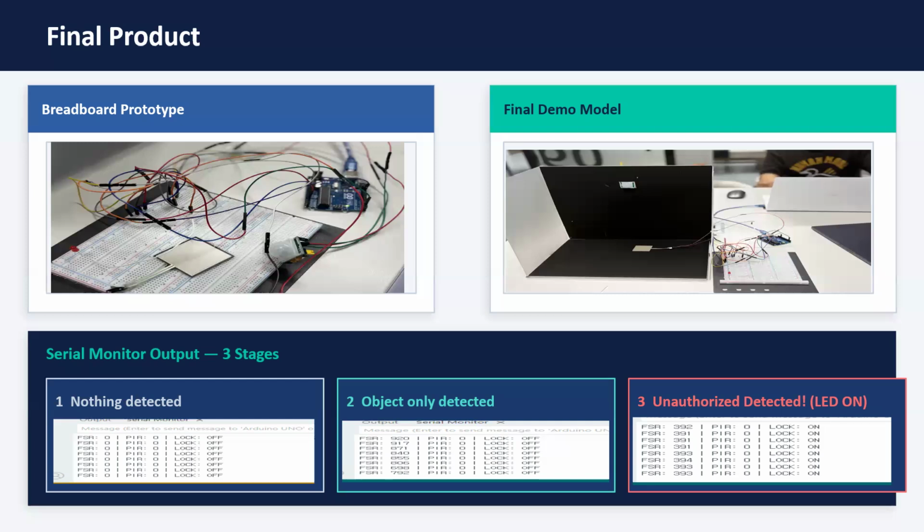Stage 2, the state occurs immediately after a user sits down and or when belongings are placed on the desk, causing the FSR value to increase. Stage 3, pressure continues to be applied to the FSR sensor, meaning belongings are still present but no human movement is detected by the PIR sensor for the preset timeout period.